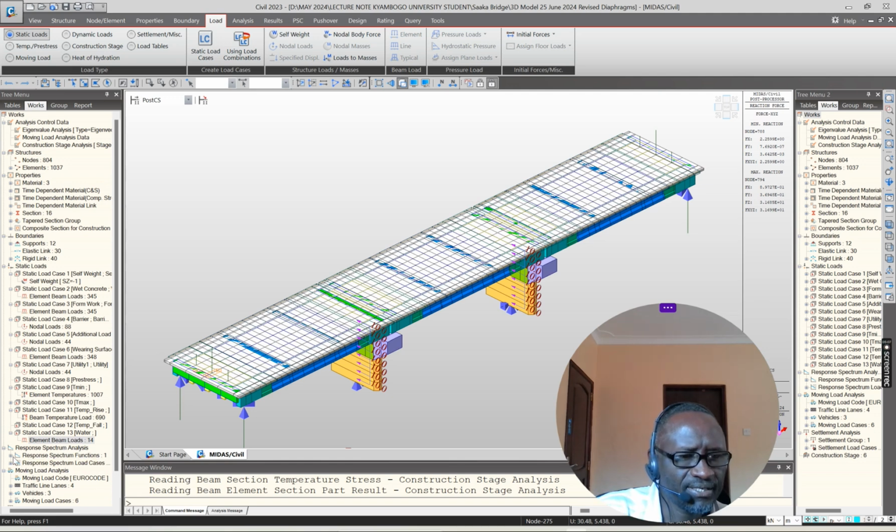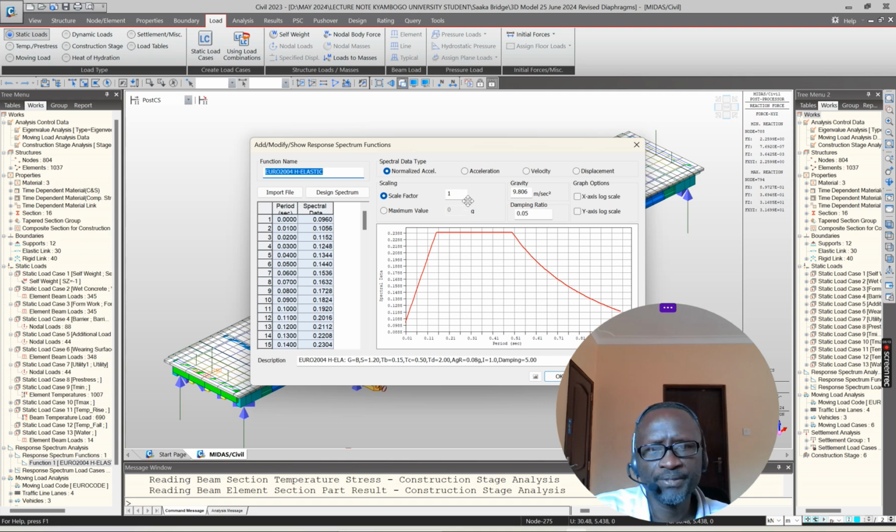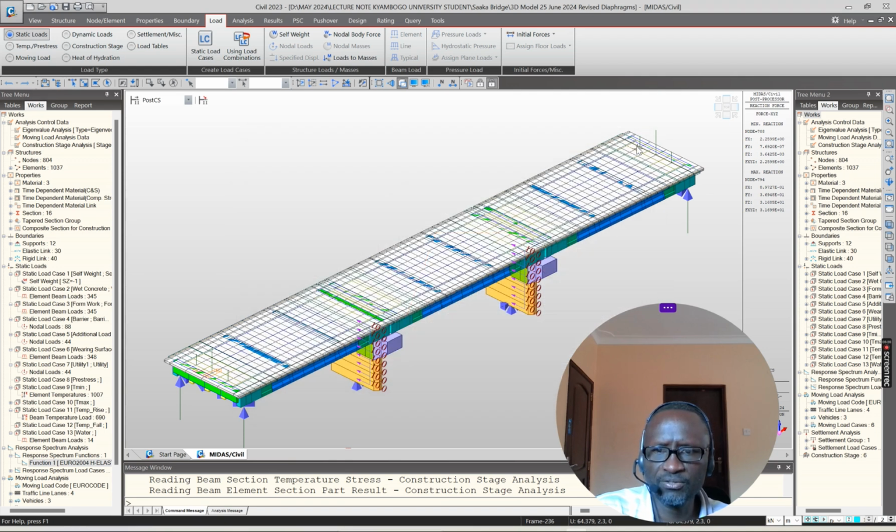And then even earthquake is very important. Nominal earthquake is specified. You have to look at all this. You find that I've given all these parameters. Normally, the input from a seismologist is very important, and from geotechnical, because the ground parameters must also be known. So these are things that we need to know.